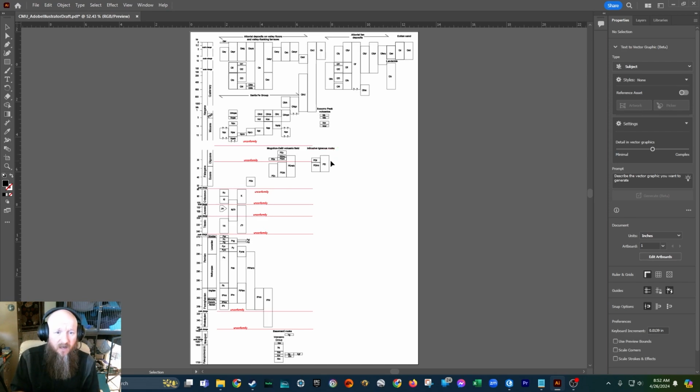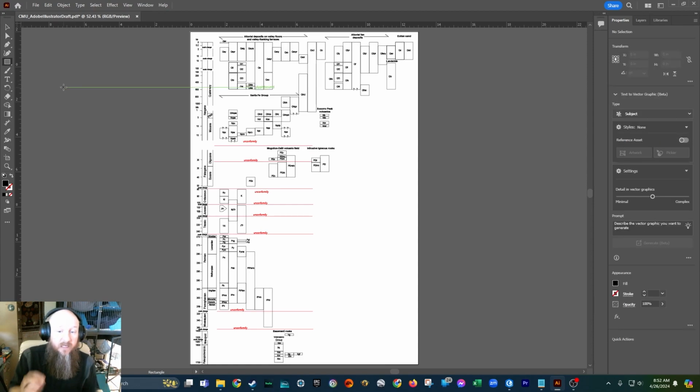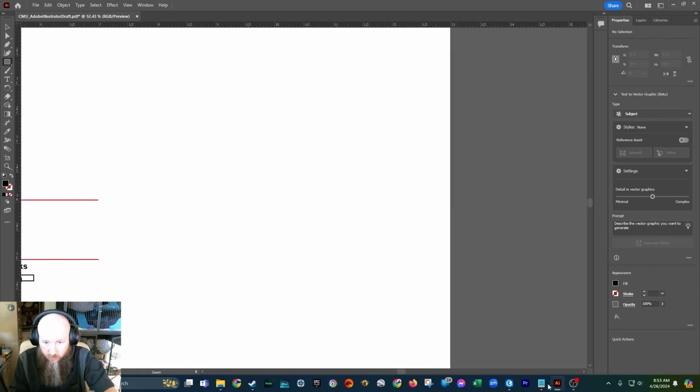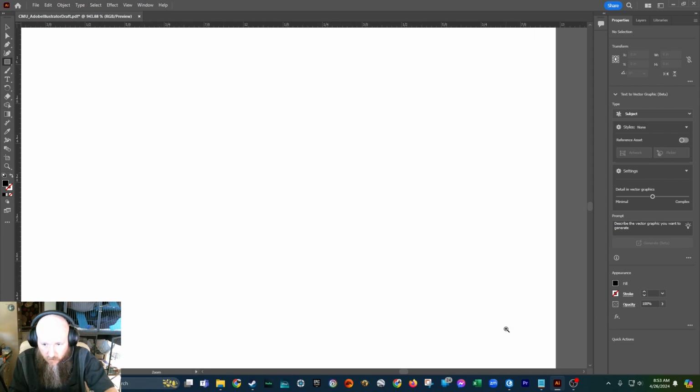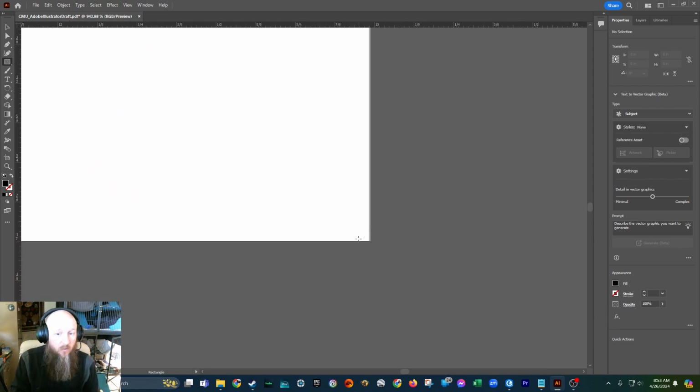So I'm going to start off by doing kind of a generic method that works. There's multiple ways you can do this, but I'm going to do the generic first because it should make the math a little bit easier. Since we need 4 corners, we don't have a corner down here. We don't have a physical object that we can georeference to. So if I zoom into this corner, if I export this as a TIFF, we don't get a neat line around the edge of this. We would only get white space here. And white space, there's nothing that we can georeference to.